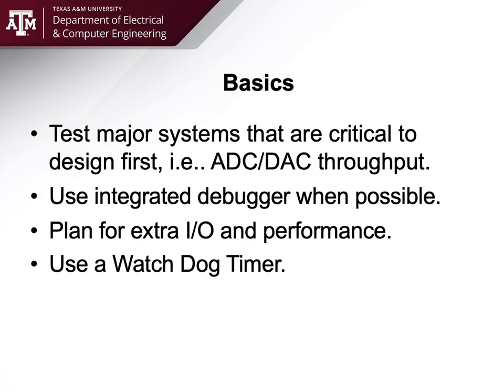And if the watchdog timer times out, say it's a 100 millisecond timer, after 100 milliseconds, if it's not been reset to 0, it will reset your main processor line. This will save your actual industrial project from causing catastrophes, because at least within 100 milliseconds, if you turned on a pump because there was a spurious noise and the program counter jumped, and all of a sudden you're executing a bunch of bad code and a bunch of I/O lines turned on, and you started turning on pumps and servo motors when you weren't supposed to, at least after 50 or 100 milliseconds, whatever your timeout time is, it gets caught and reset.